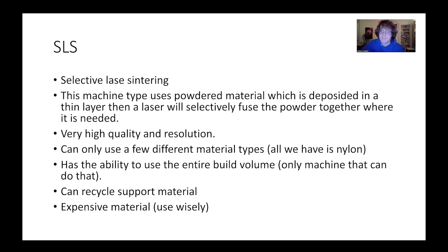Okay. Which is really interesting because then you're able to recycle it, which is nice because this is the most expensive material type that we have more or less. You can't necessarily use it as a 100% recycle sort of thing. After you remove it from the part, after something is printed, recycled powder gets a little bit clumpier. So you mix it in with some new powder, just so that it's a little bit smoother to be dispensed in the machine. But for the most part, yes, you can use all of your unused support powder again in another print, which is helpful.